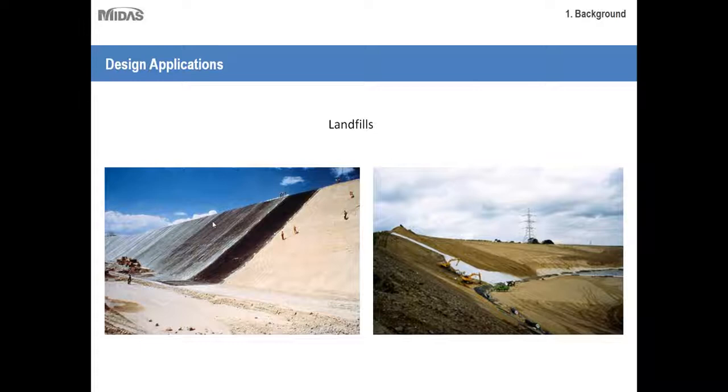If you're working in an area with large amounts of rainfall, what these will do is keep the water from seeping into your slope and compromising its stability. But if you work in an area that's relatively dry, then you wouldn't really need to worry about that. So once again, your project area or site conditions determine how you would design your slopes. In addition to the soil you're working with, another key factor to take into account is rainfall.